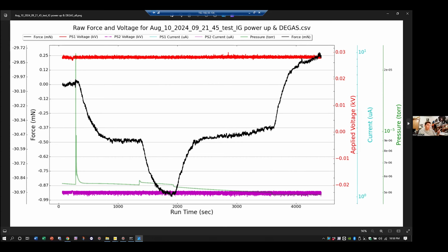If you get your ion gauge to stasis and you run from here forever, things are good. But if you just switch on your ion gauge or punch up a degas, you can get all kinds of false thrust. This is a millinewton of false thrust, which is literally nothing but a bunch of ions dumped into the system. That's another way the universe can lie to you that you just don't expect.